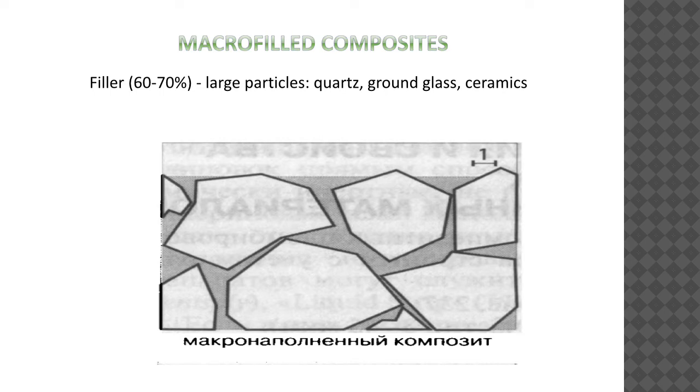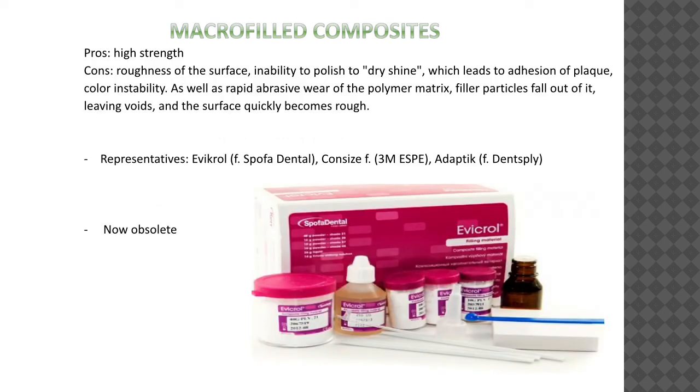Macrofilled composites. They have a filler of 60 to 70% of mass with large particles like quartz, ground glass, or ceramics. The advantages of macrofilled composites are the high strength, but they have a lot of disadvantages, such as roughness of the surface, inability to polish them to dry shine, which leads to adhesion of plaque, and instability of color, as well as a rapid abrasive wear of the polymer matrix.